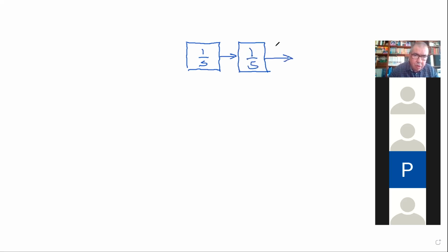And we have y equals x1. And then you have here the velocity that you don't measure directly. So you measure just the position, and you also have access to the value of u because you are imposing it. Now we want to feed back the position and the velocity. The position we measure, but we don't measure the velocity. So we want to estimate the velocity. So how can I get an estimate of the velocity?